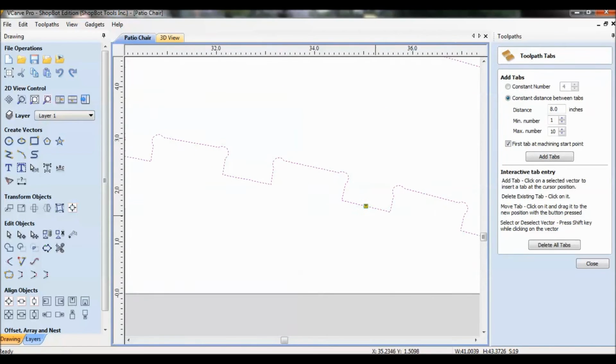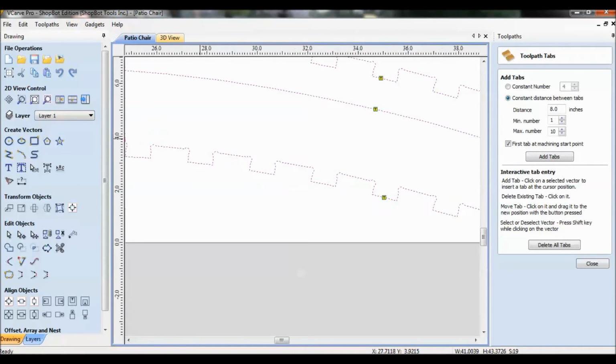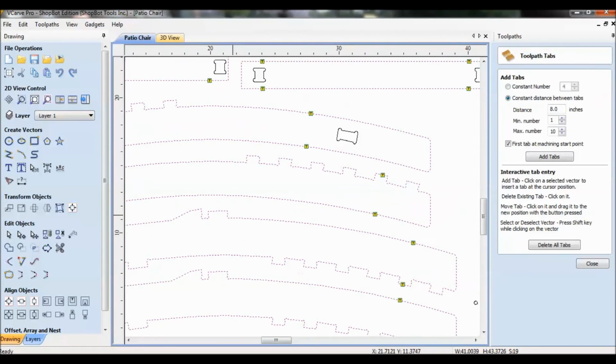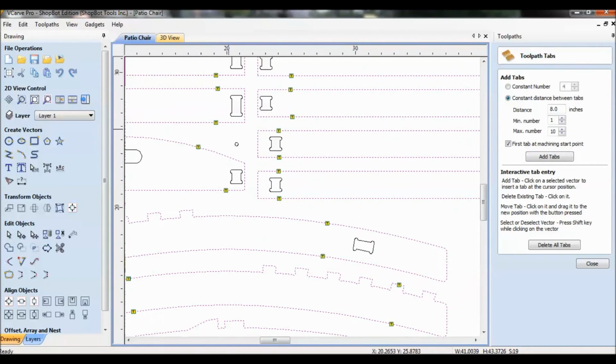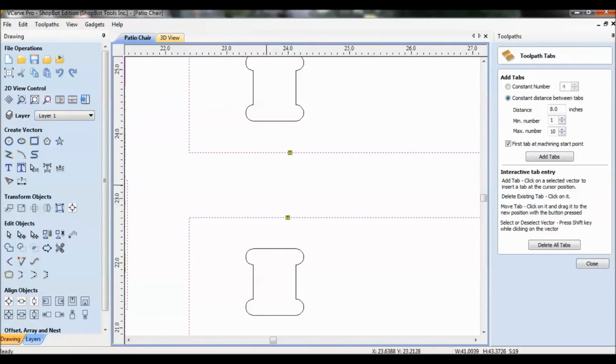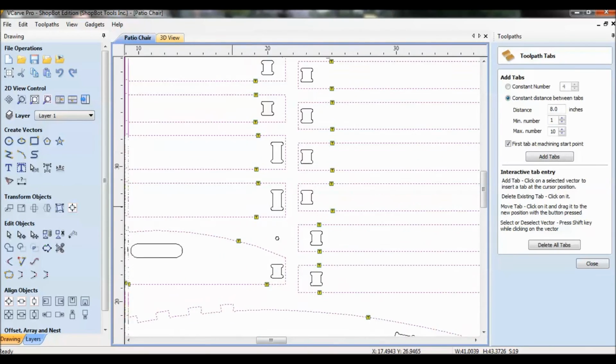I know this being on the top of this tenon, if I go to sand it and I don't get it all, I take a little too much off or it doesn't look pretty, it doesn't matter. It's going to be down inside of a glued up joint. So I'm just going to kind of look over. I got these all opposing each other because there's not going to be a whole lot of material left in here. So if I have tabs across from each other, it'll help build strength.